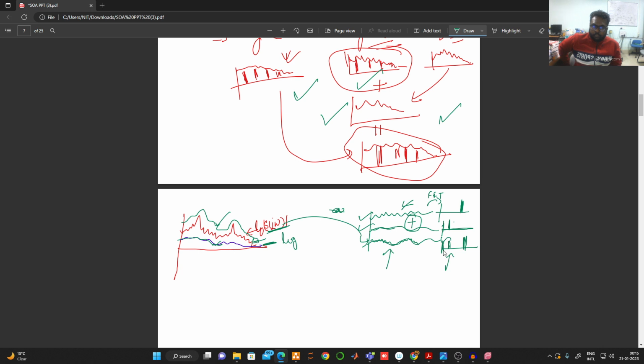I do not want that. Rather I just want this lower part. So how can we do that? Because it now has these higher frequencies and the lower part also. So for that purpose we must use some low pass filter. Okay, so that we can do with inverse Fourier transformation. So what is happening basically? Initially we are doing the Fourier transformation of s(t), then you will get S(jω).